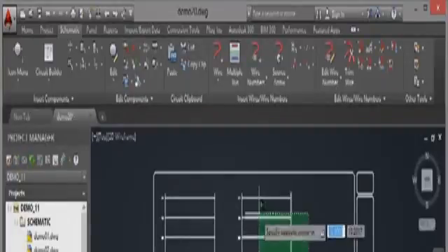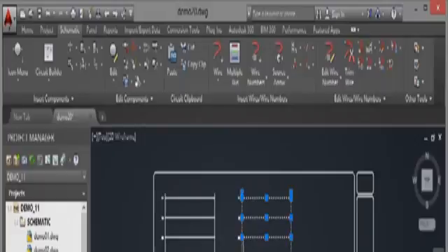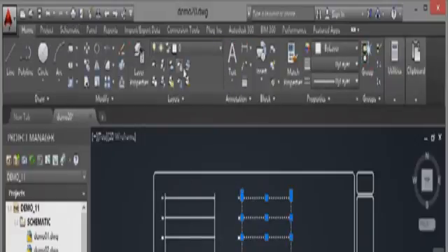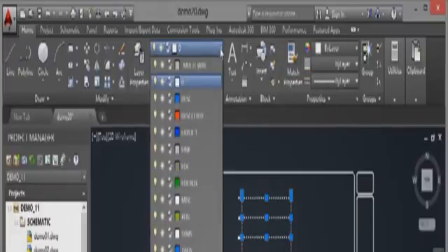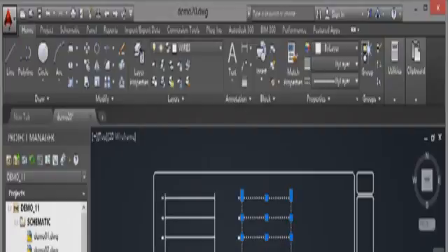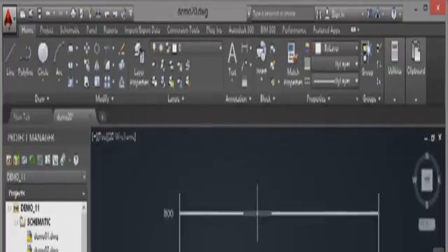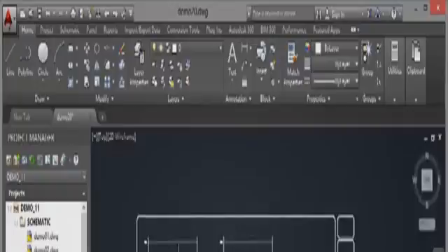So what I'm going to do, I'm going to zoom out, and I'm going to select all of the lines, not the numbers. If I miss that line, just get that vertical line there as well. I'm going to go to the Home tab on the ribbon, go to the layer pull down, and make sure that they are on the wires layer. So if I hit escape now, zoom in, hover over there, that is on the wires layer. So that has now replicated our ladder over here.